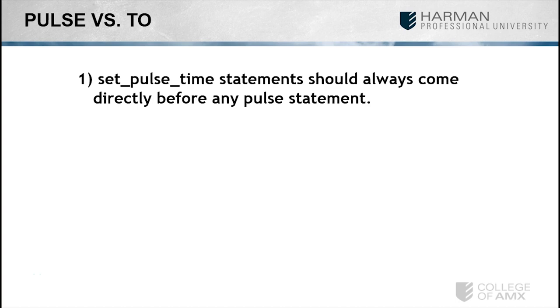A half second is not appropriate for all IR functions. Because IR codes vary, and vary in length or time specifically, a 0.5 second pulse may be too long for some device codes, and the result would be multiple codes firing off when not warranted. Similar to when pressing a PTZ button on a remote, sometimes multiple codes fire off, and instead of getting the camera to shift once, it shifts 2 or 3 times, for example.